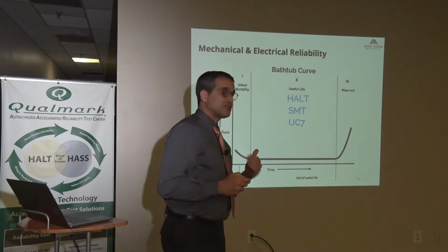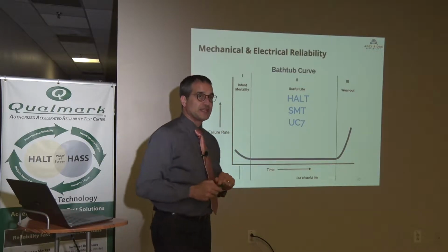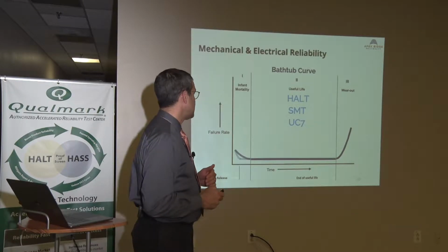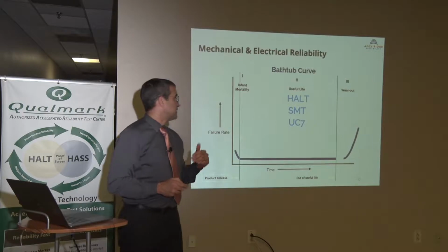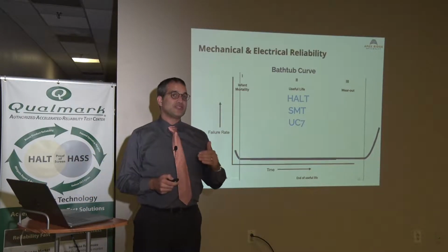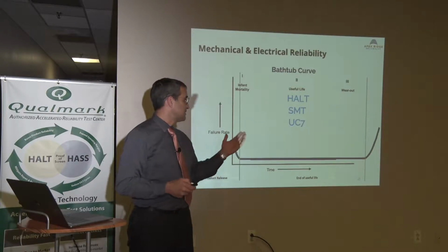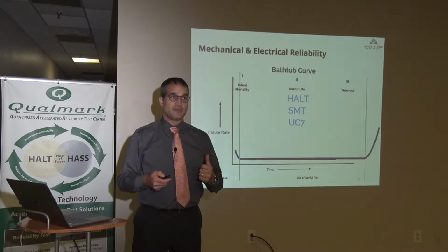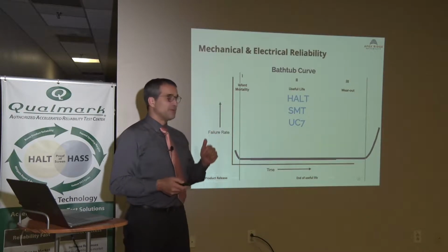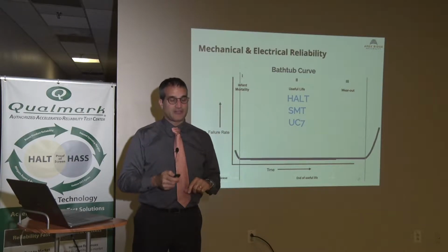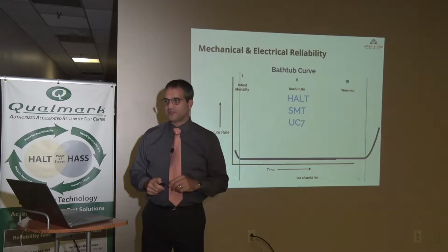So it will also have the peripheral effect of helping with the quality side, because by default, any of those margins in normal use will also affect quality. And it will, of course, as I described, if you include in your use case using time for accumulated stress, improve wear out as well. So you do have opportunities to help the bathtub curve for the whole population through their entire life. But I will emphasize that it is the normal use period and the reliability during normal use life that I've seen gain the greatest benefit.